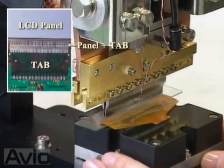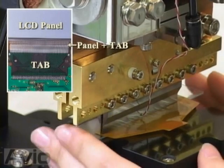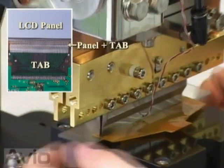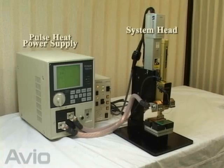Furthermore, tab is thermocompressed to complete the module assembly process. While control of temperature, time, and pressure is important in thermocompression bonding, the pulse heat unit from Avio is superior in all these aspects, providing highly reliable bonding.